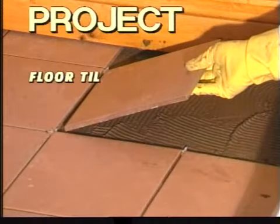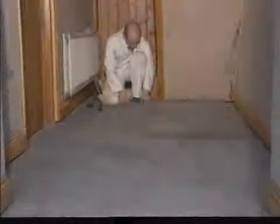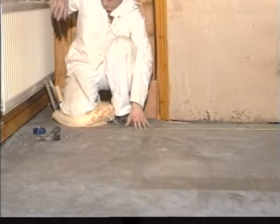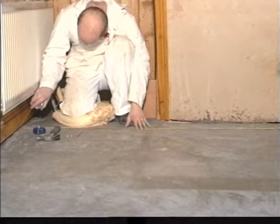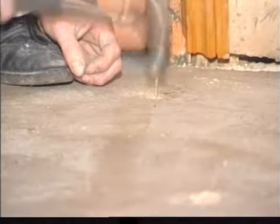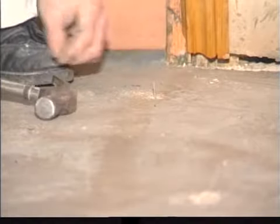Floor tiling. Measure the width of the room at one end. Find the halfway mark and mark with a nail. Repeat this process at the other end of the room.